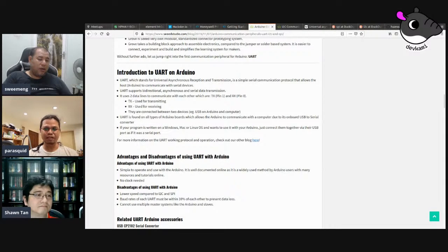Like many of the tiny 85s, for example, a 6-pin, very small microcontroller, it's great for NeoPixels because it's fast enough, but it doesn't have UART. You can have SPI and I2C, they share pins, so you can only choose one, but it doesn't have UART. You have to bitbang the UART. So it depends on the microcontroller. Yeah, correct. So the first thing is check your spec. But chances are, if you're a hobbyist like me and you use Arduino, then we already have a standard.